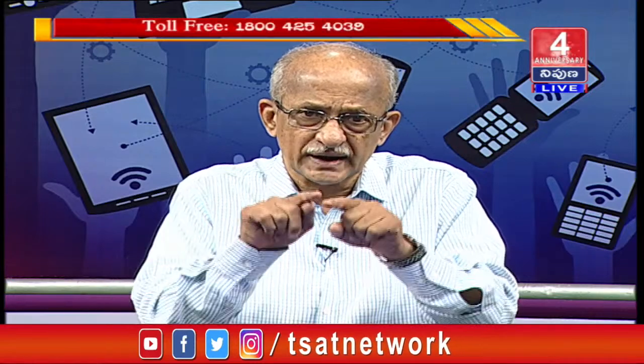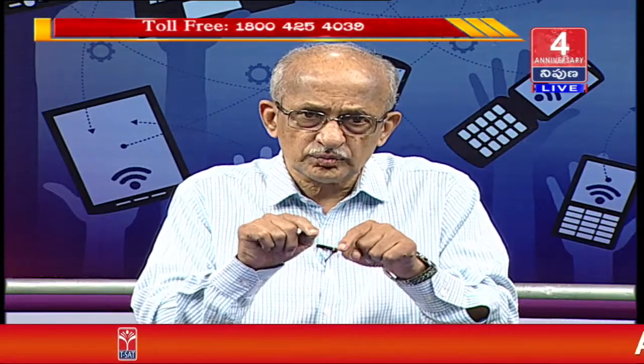The IO pads, the places where the inputs have to be applied and the outputs have to be taken from the chip, are actually left exposed, so that the metal contacts on what is known as a load board can reach them. The chip is manufactured with a certain dimension of silicon, and corresponding to that dimension, there will be a probe.